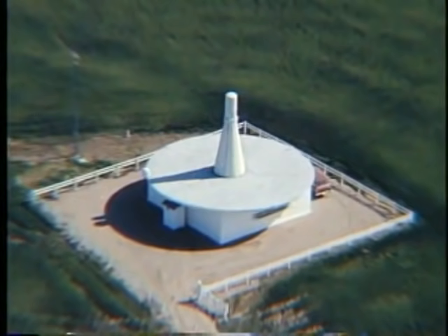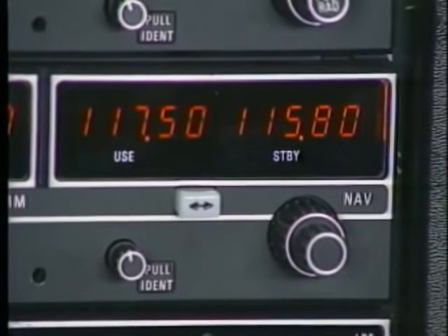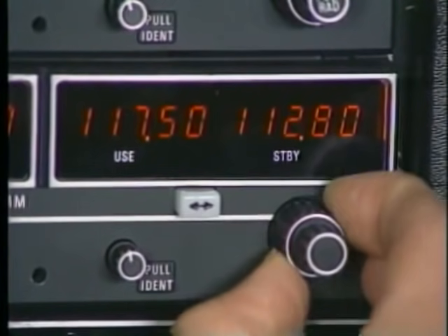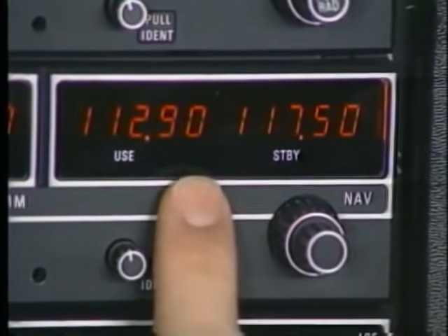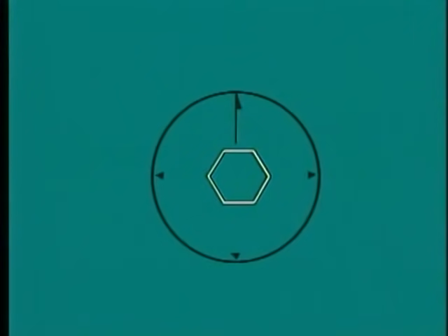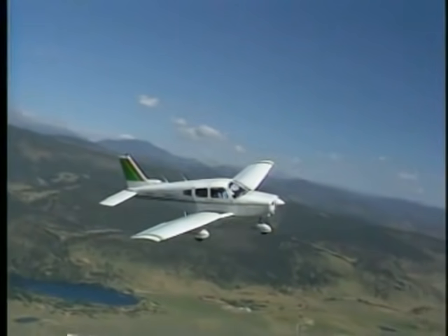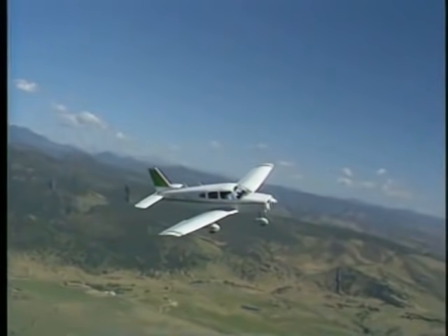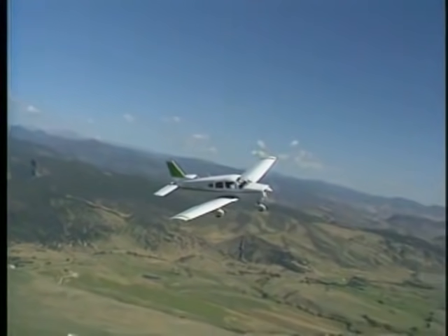Properly equipped civil aircraft can use the VOR portion of a VORTAC for course guidance and the TACAN part for distance information. This is accomplished through frequency pairing, which means that when you select the VOR frequency, the UHF frequency of the TACAN is automatically selected by the DME equipment in your aircraft. To civilian aircraft, a VOR DME nav aid works like a VORTAC station. When you select the proper VOR frequency, your DME is automatically paired to the correct UHF frequency.